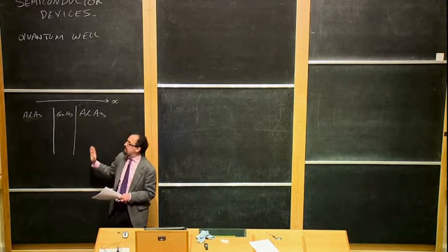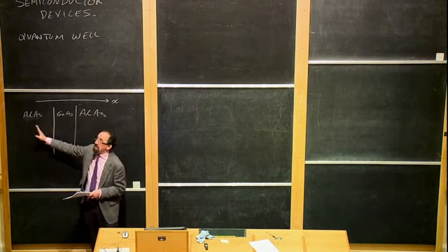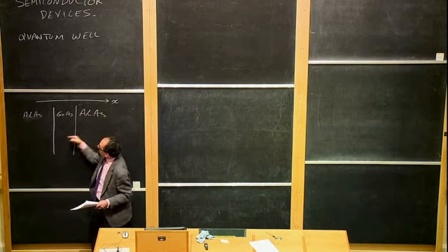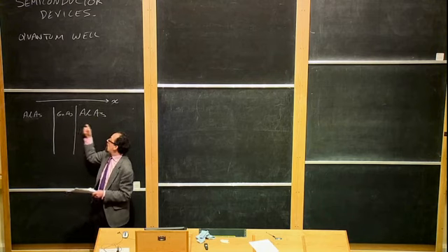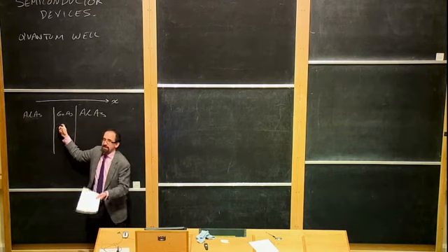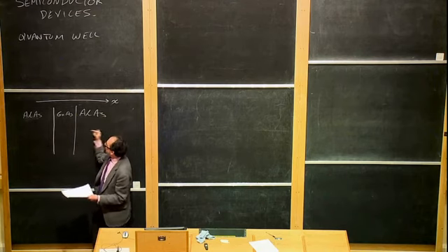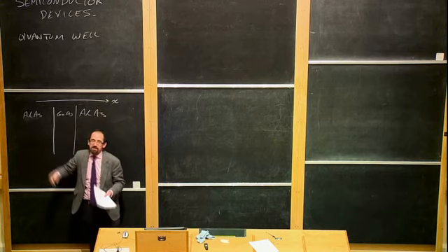The reason that makes things very desirable is it means that you can line up the atoms directly between the gallium arsenide and the aluminum arsenide and basically have just one giant crystal. And as you walk through the crystal, the only thing that changes is that in going from this material to this material, all the aluminums get secretly replaced with galliums. Okay? So it just looks like one big crystal of one material, but over here you have aluminums, here you have galliums, and then you're back here and it's aluminums again.